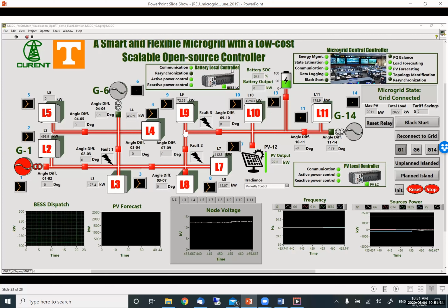So do you run the risk of damaging any equipment with the sudden onrush of all that current? You are saying whether the inrush current will damage the device? Yeah, is it possible? Have you guys thought about that? We do, and this is related to our design. We have smart switches that divide the load into smaller sections, each around 200 or 300 kilowatts.